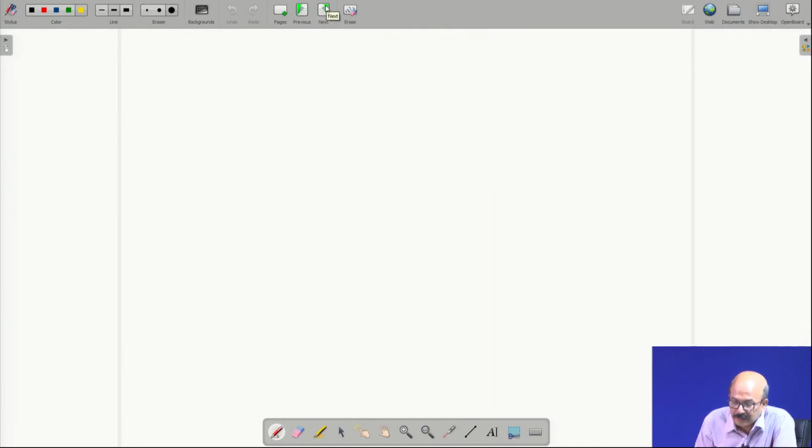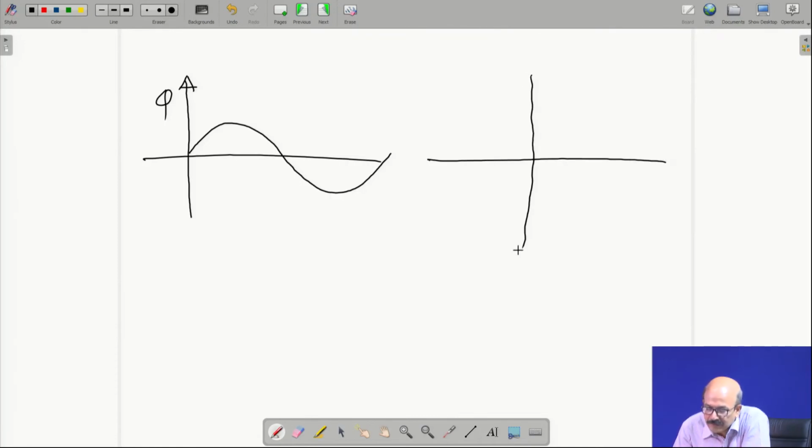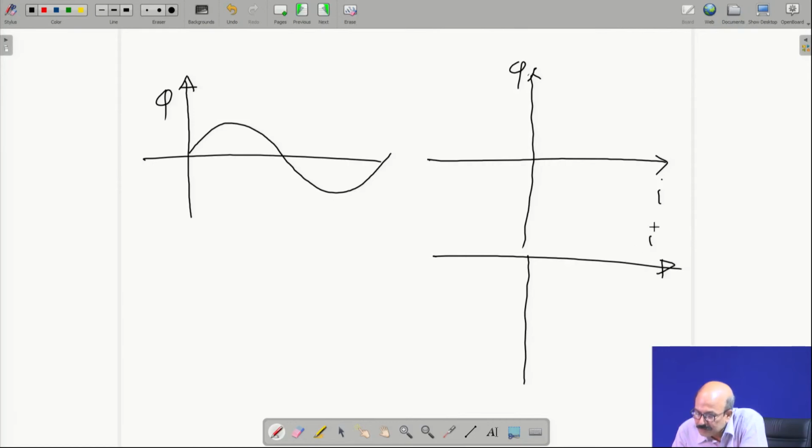Okay, next page. Let's look at the next page. So, when we consider the hysteresis, then something interesting happens. What happens? You have a flux, still the same sine wave flux here, and on this side you can have the flux and current characteristics, phi-I. So from flux, using the phi-I characteristics, we will go to I versus omega t, the nature of the current.